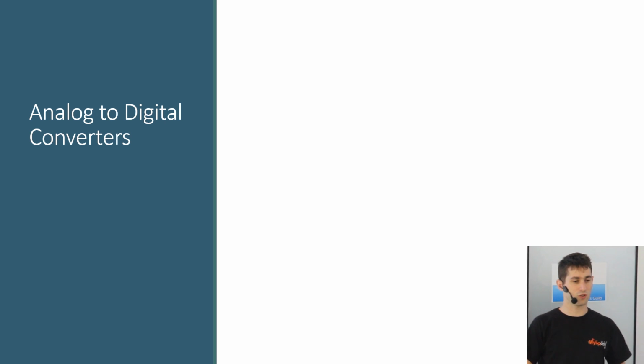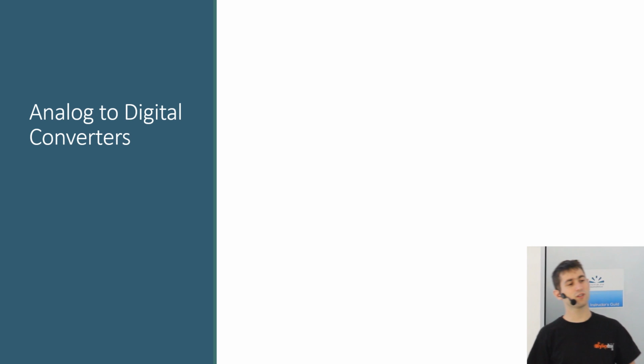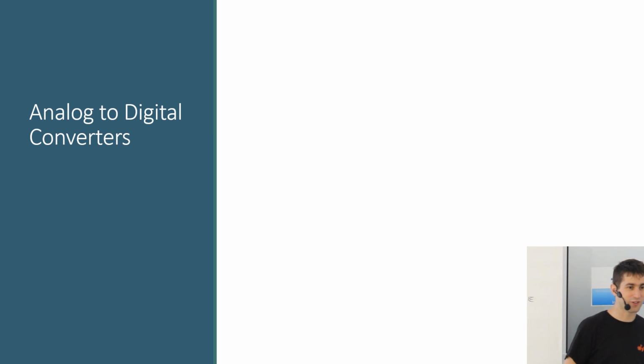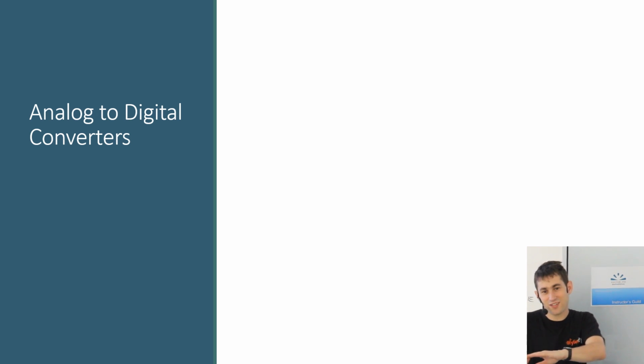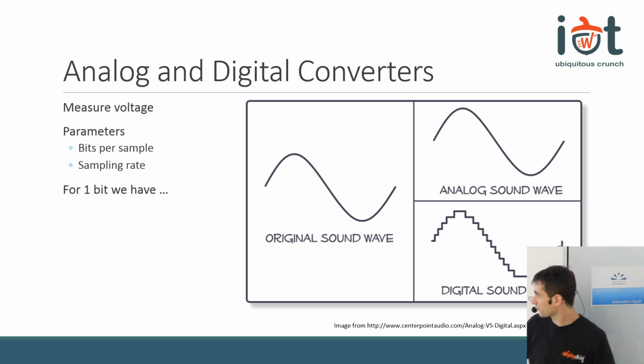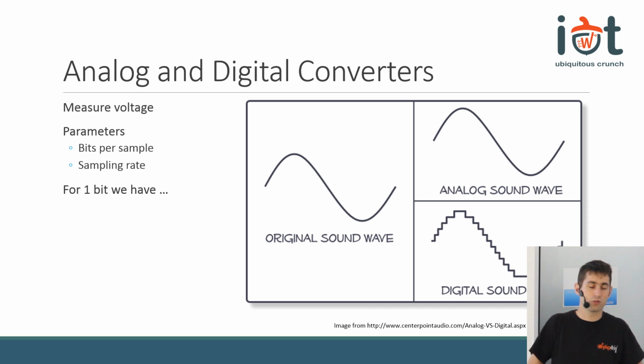But in my presentation, did we discuss an analog to digital converter? No, that was the slide with the red lines and the sine form. But talking about the pins, did we see an analog to digital converter until now? We did. The GPIO input pin is a 1-bit analog to digital converter. It takes an analog signal, measures it, and decides on 1 bit if it's below half or above half.